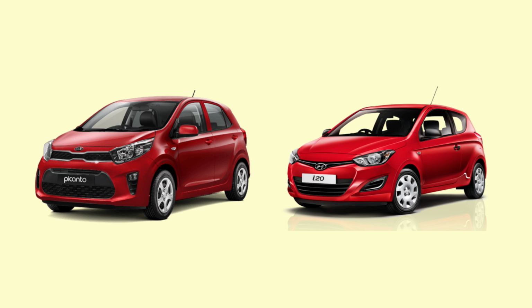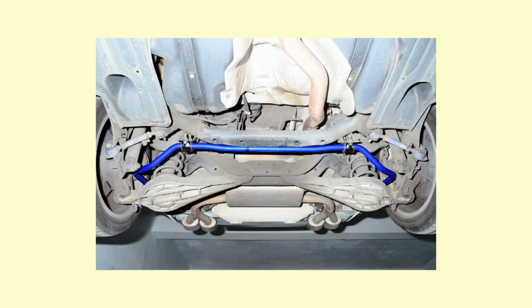Whilst driving techniques can help, sometimes the car setup will play a big role in understeer. Most stock cars are designed with a tendency to understeer because it's easier to control compared to oversteer, which requires more precision. Let's look at some mods that can help fix this, starting with the simpler ones in terms of assembly. Firstly, you can install a rear sway bar. It stiffens the connection between the rear suspension points, helping reduce body roll during initial turn-in and allowing the rear to rotate more.